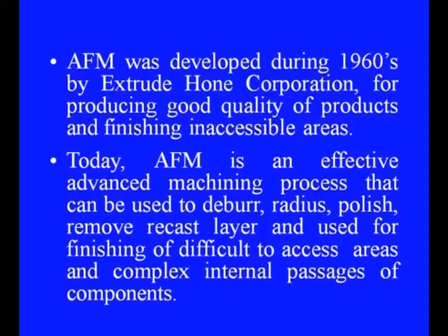With these problems or limitations of the conventional finishing processes in mind, abrasive flow machining was developed during the 1960s by Extrude Hone Corporation of the United States of America for producing good quality products and finishing inaccessible areas. Today, this process is an effective advanced machining process that can be used to deburr, radius, polish, remove recast layers, and also for finishing difficult to access areas and complex internal passages of components, which I have just now discussed.